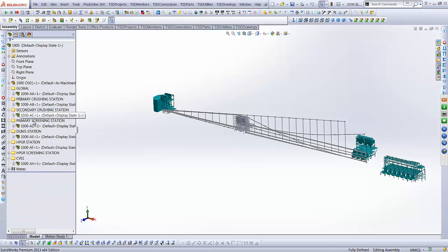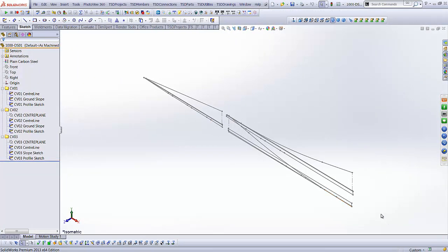So if I've got people working at lower levels, they've got those assemblies open, I open up the top level assembly and I change the driving sketch, they will be notified that a change has occurred, and they will be asked if they'd like to update their model, and the position of their structure inside the project will move. And then you will continue on working. Or alternatively, you can have some changes that will change your structure at this level. And that could be positioning, but you could also set up your grids for your major structure in the same driving sketch part. So you might have a grid here and a grid there to drive your structures.